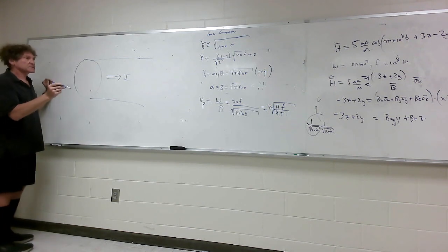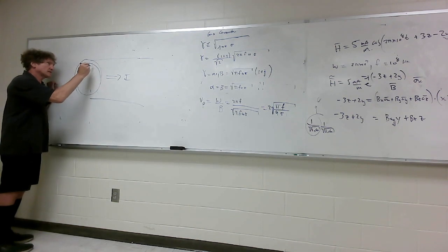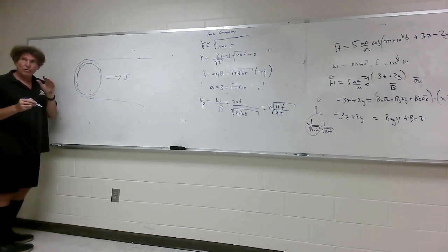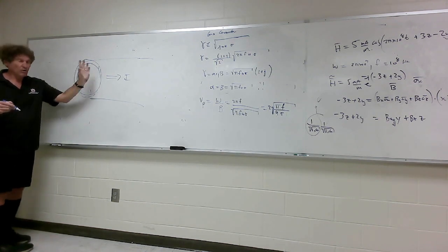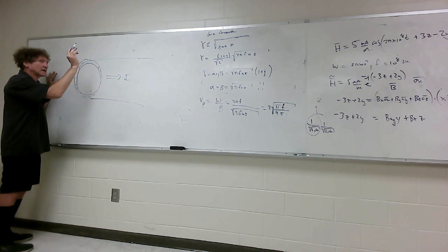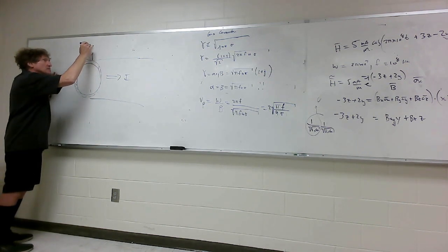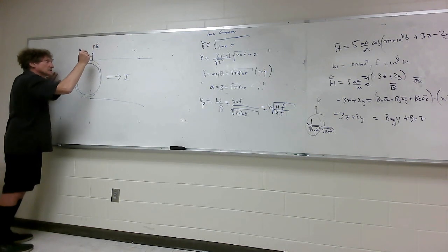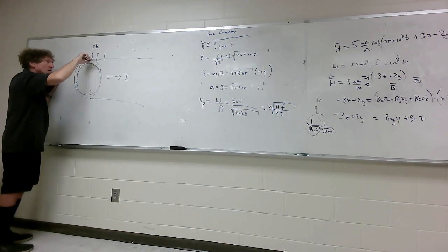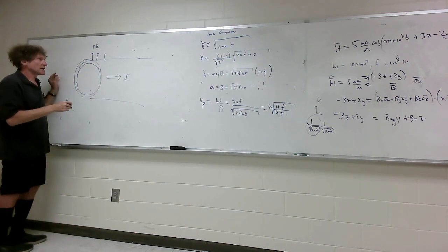What we're going to see is there's a skin-depth effect. All the current is going to be right on the edge of the wire, right where the wire intersects free space. And it'll be all the way down there, but there will be a wave, and what actually happens is that there is going to be an electric field that is almost perpendicular to this wire, and there'll be an H field that's circulating in the azimuthal direction.